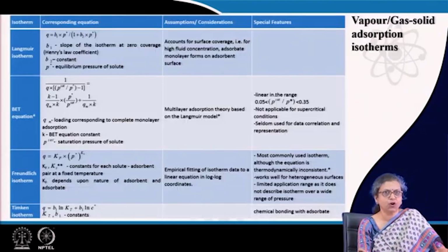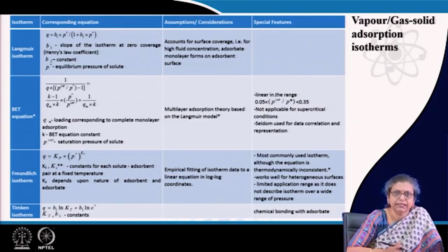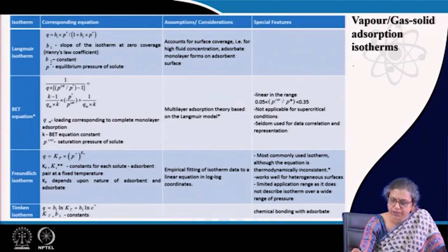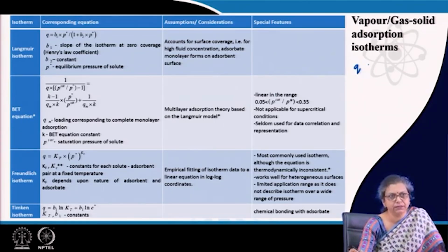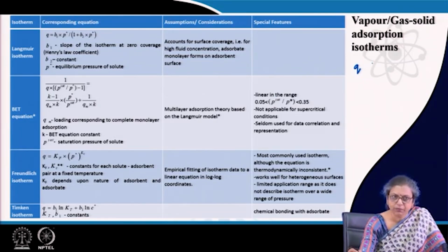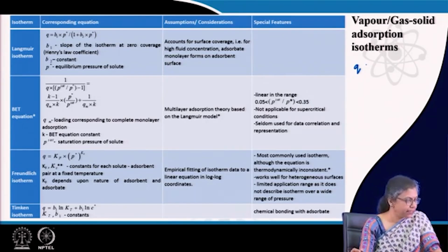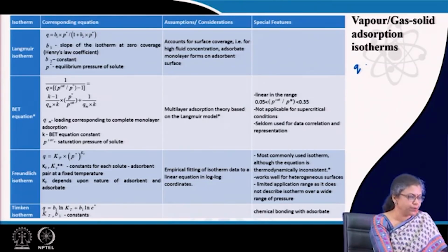Well, for adsorption, just like there are equations available to generate vapor-liquid and gas solubility data, in the same way there are also equations available to express Q in terms of P and T. Now, remember one thing: the most common way of expressing adsorption is in terms of isotherms.